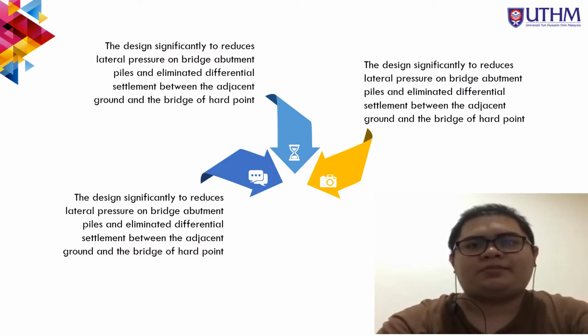Hello, my name is Muhammad Yusri bin Yusof, and I would like to present the design and analysis based on this case study. Geogrid reinforced pile embankment with individual pile caps was planned and constructed in this project for usage along the railway track and rail bridge approach transition for embankments 4 to 8 meters high. The application of geogrid reinforced pile embankment is to ensure there is no sudden change in settlement profile.